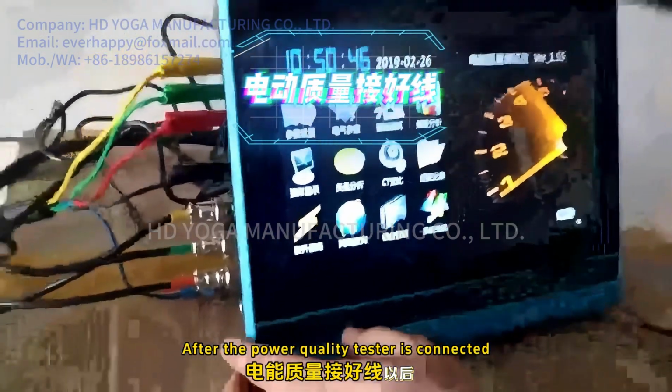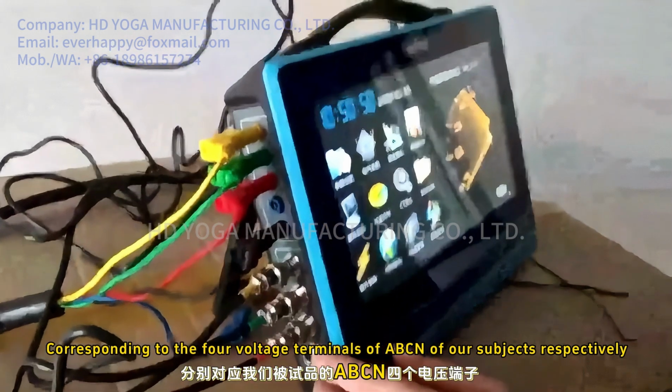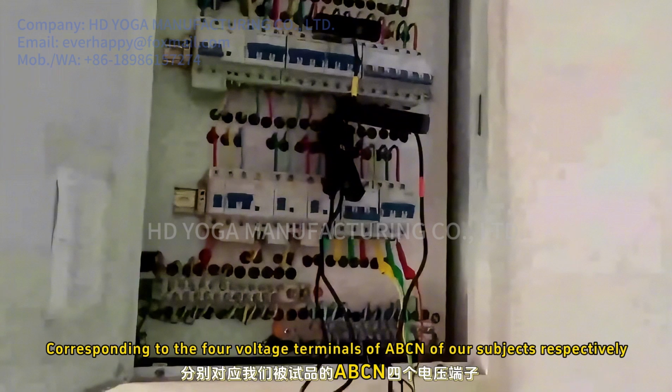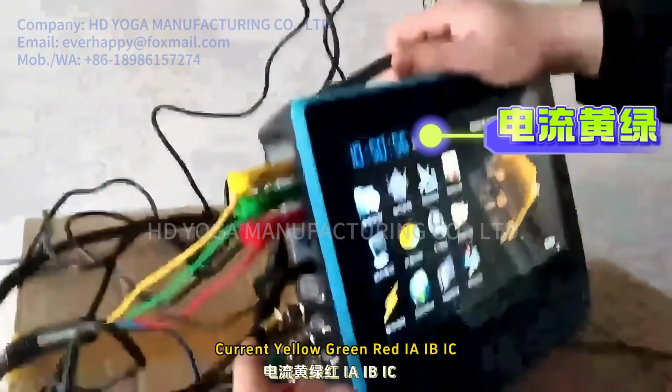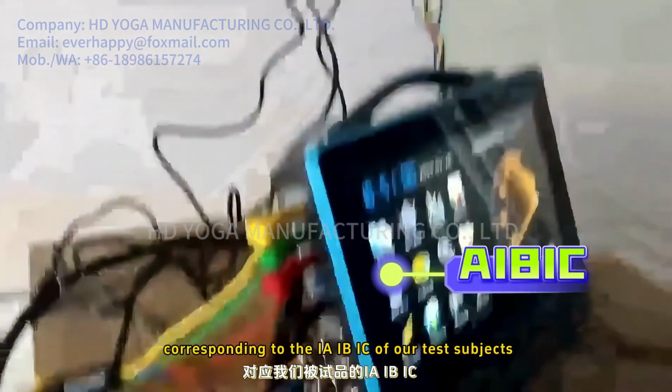After the power quality tester is connected. Voltage yellow, green, red, black, corresponding to the 4 voltage terminals of A, B, C and N of our test subjects respectively. Current yellow, green, red, IA, IB, IC, corresponding to the IA, IB, IC of our test subjects.